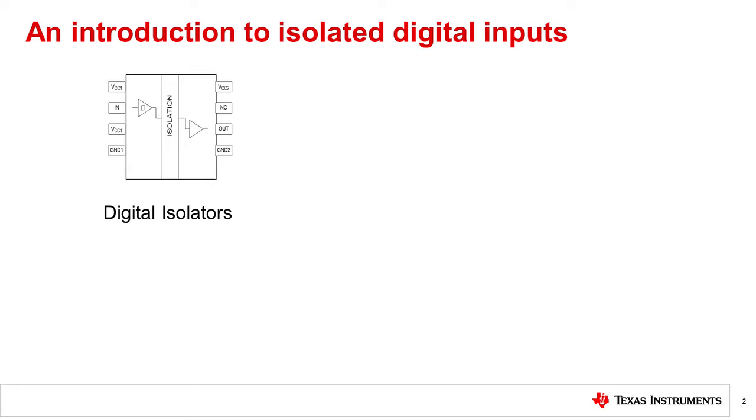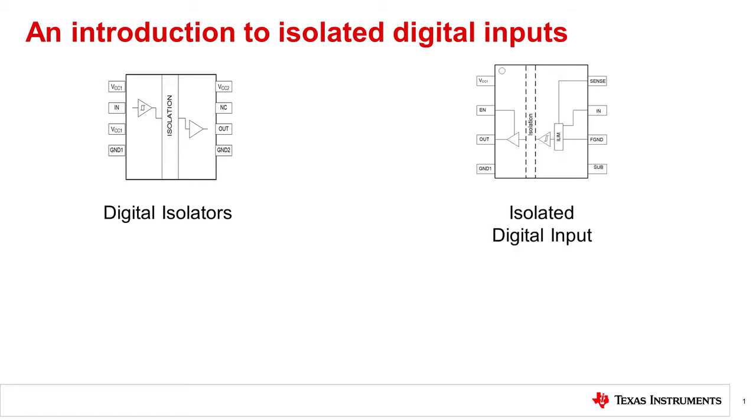What are isolated digital inputs? In previous videos, we've discussed galvanic isolation and the inner workings of digital isolators. In this video, we will introduce a different isolation device, the function of isolated digital input. Unlike the standard pinout of more commonly seen digital isolators, isolated digital inputs act as digital receivers with wide input ranges and a modified internal architecture that makes them uniquely suited for digital input module designs.